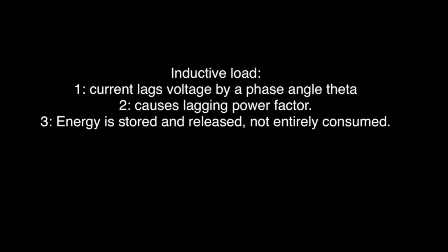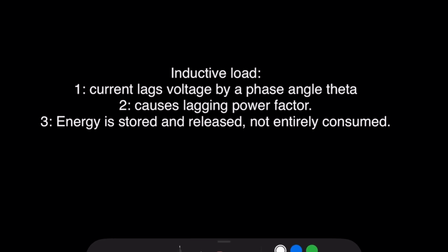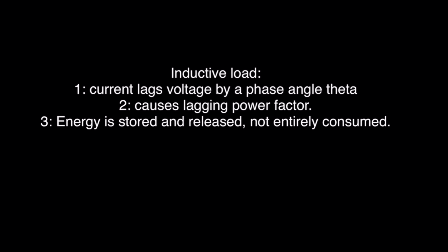Okay, so this is a repetition. Inductive load has three characteristics. Current lags voltage by a phase angle theta, causing a lagging power factor, and finally, energy stored and released is not entirely consumed as we had in resistive loads.